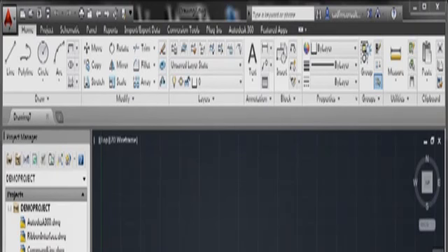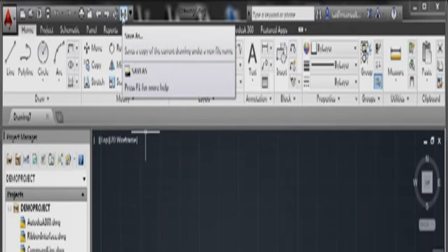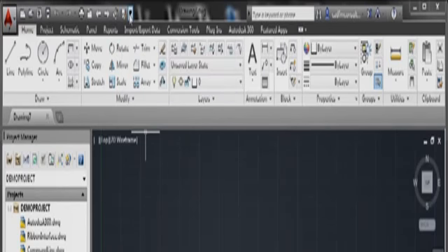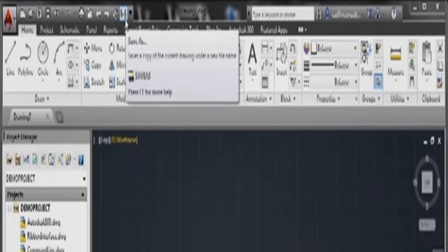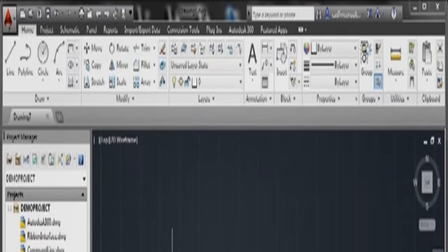You'll notice I've been using Save As a lot in this particular section as well. Save As is not a default setting in AutoCAD Electrical. You can see there it is, up on the Quick Access toolbar, Save As. If you click on this little flyout here, you'll see that Save As has a tick next to it. All you've got to do is select Save As in that menu, and you'll see the tick appear. The tick indicates that Save As is displayed on the Quick Access toolbar. So when I click on Save As, it gives me the option to save the drawing as and save it in a folder somewhere. I'll just cancel that now.